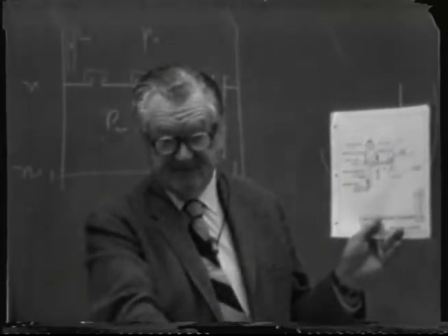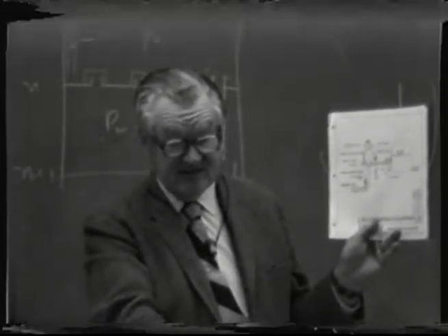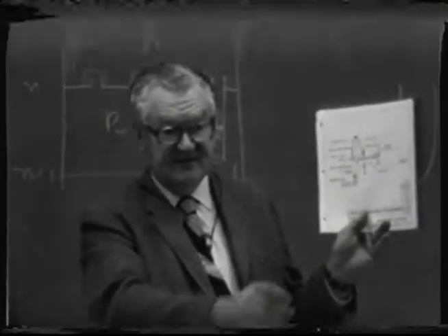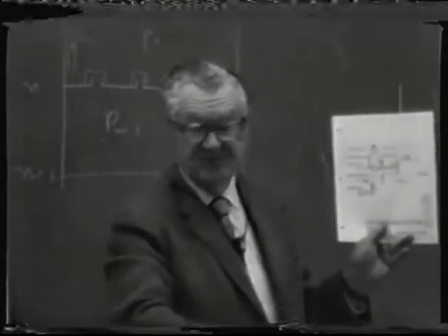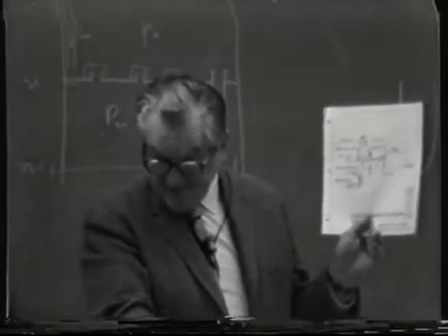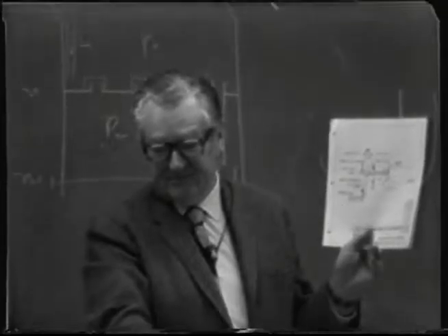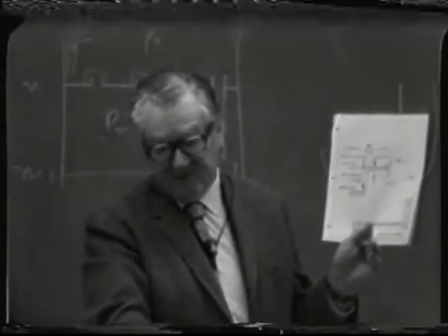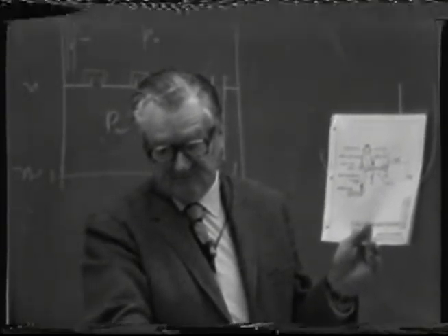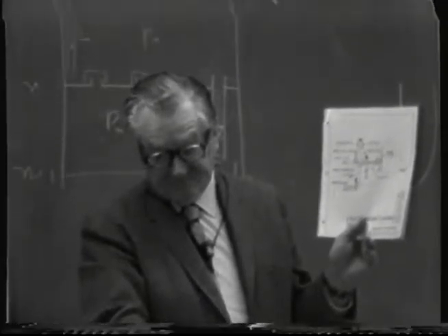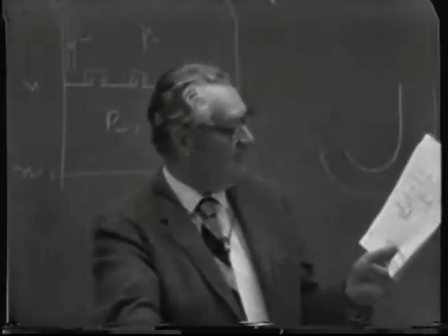And the amount of steam that's created, or the water vapor from evaporating stillage, is mixed with the main stream of steam from the boiler and enters the base of the distilling column as the heat energy, or the vapor, for operating the still. This vapor liquid separator is where this goes on, right? Yeah, that's what it is.